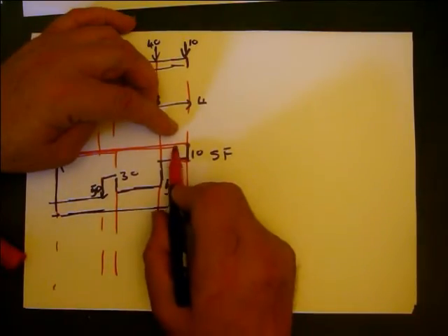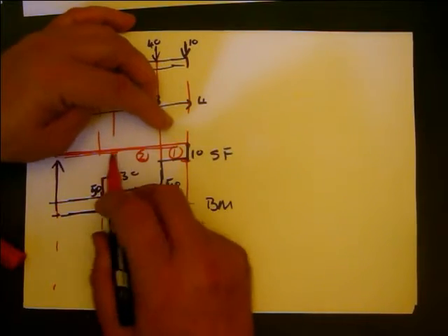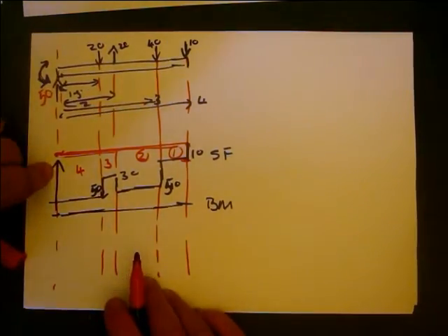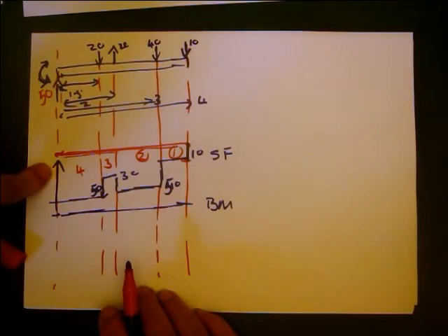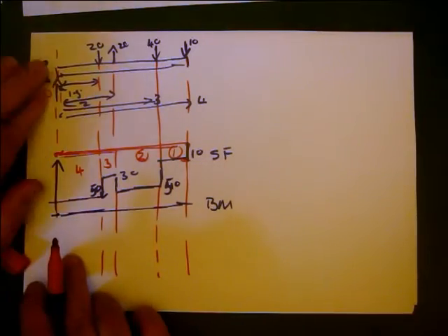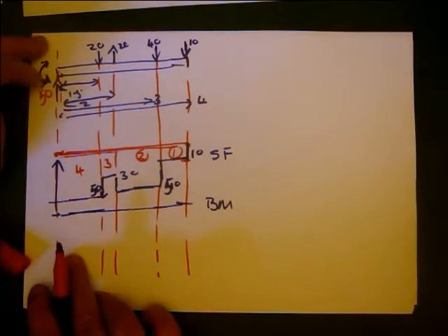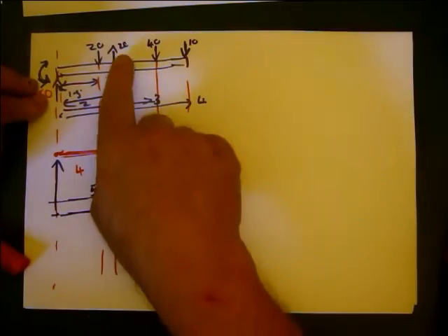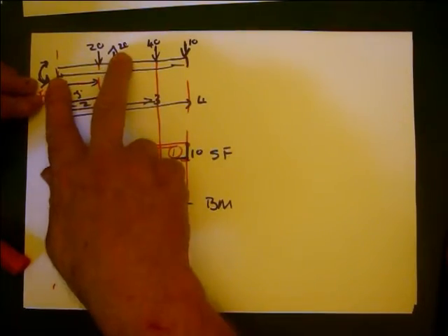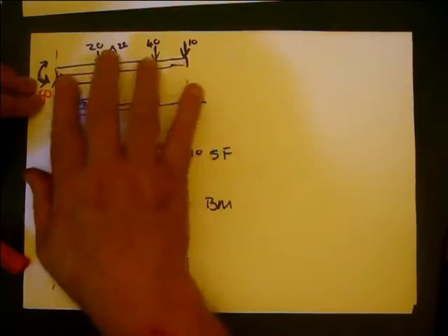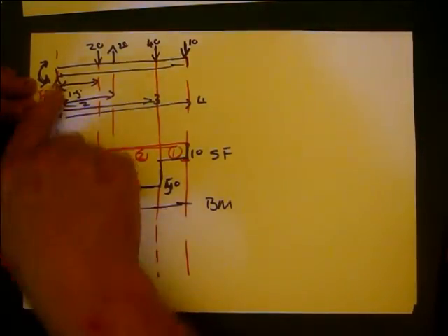We're going to break this up into various areas, 1, 2, 3, 4, because we've got to find out what the fixing moment is. The fixing force is the force upwards applied by the wall. Let's just check. We've got 50 here and 20 here, so we've got 70 acting up. We've got 20, 40, 10 down there, that's 70 acting down, so that's right.